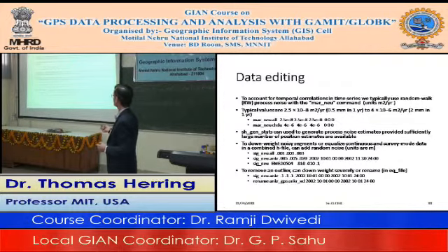A typical value that we would use is 2.5 by 10 to the minus 8 meters per square root second. That's about 0.5 millimeter in a year. That's actually a really good station. And then the worst stations are something like 4 or a bit higher. That's about 2 millimeters in a year of motion. And that's to represent the random motion of stations as you go across.